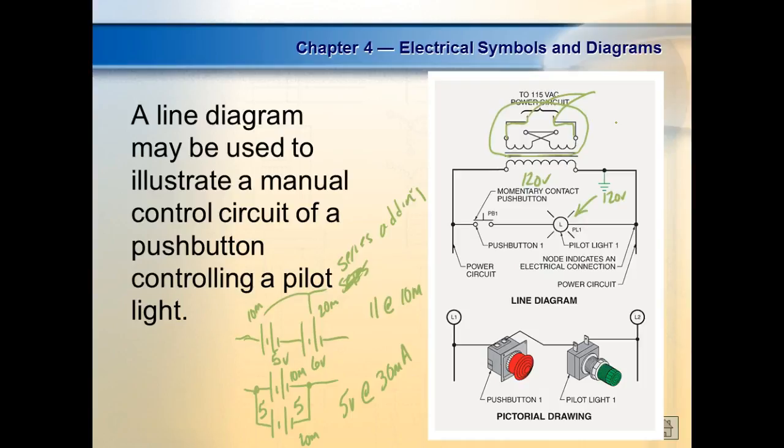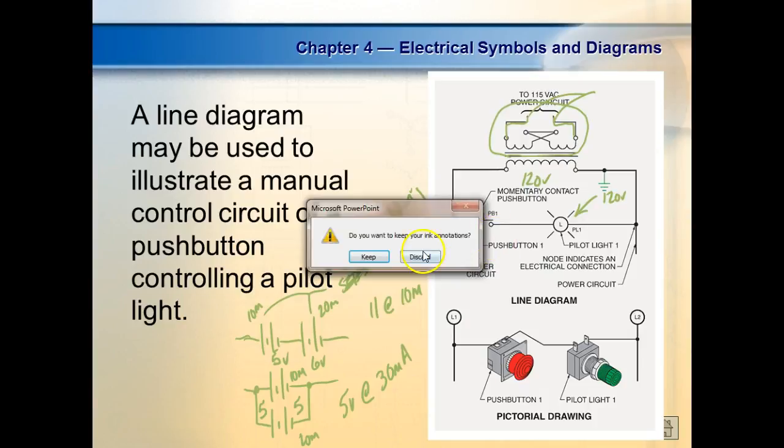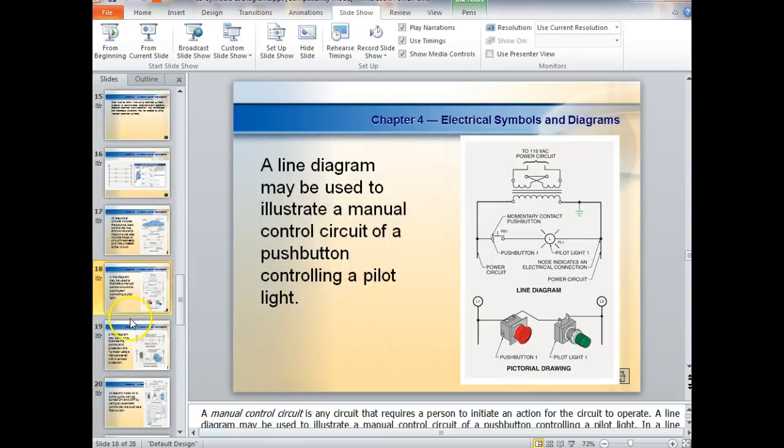It's just like at your house. When you put circuit breakers in your panel box, what should you do? You should go from side to side, side to side, side to side. You shouldn't load up one side and then move over to the other. Because if you do that, you're going to put all your 120 volt loads on one side of your transformer. Right? You understand that? So you need to stagger the loads, or even the single phase loads. Everybody follow me so far? Have I lost anybody?